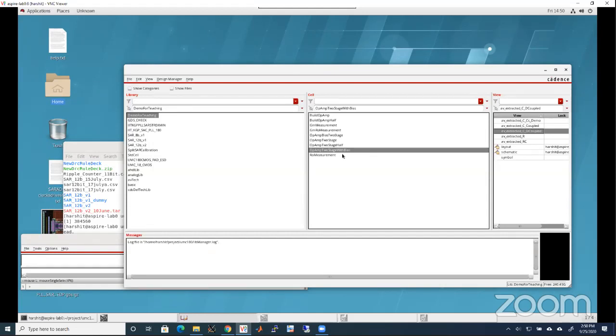Keep in mind, an op-amp layout cannot be done in one go. When I said the layout took two days to do, we had to do multiple extractions to finally converge on the final layout, because we have to extract and make sure that everything is perfectly matched. So that means we did that.